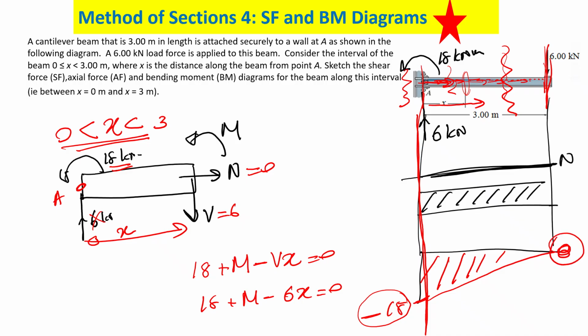Okay. And I forgot to tell you in the previous one, here you have a why. Let's see why we need this internal force diagram. In the previous one you saw something like this for shear force. So you can see which sections your shear force is higher and critical, and you don't have to have the same thickness of the beam throughout.